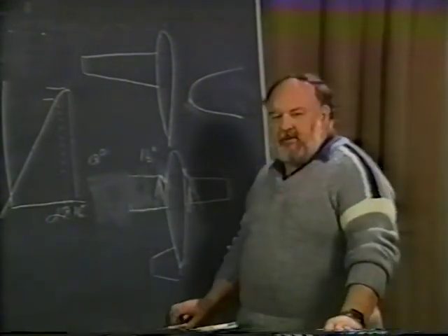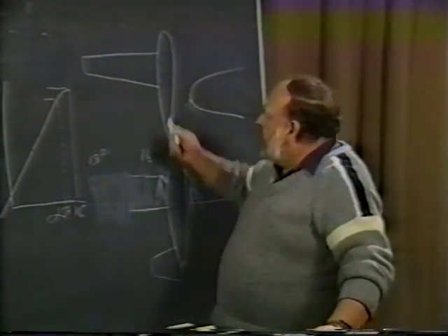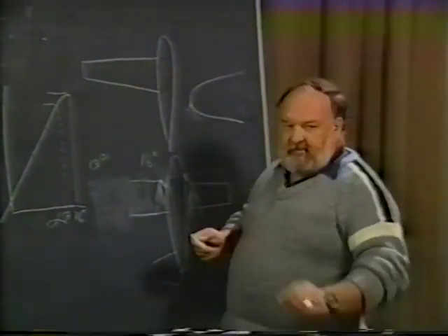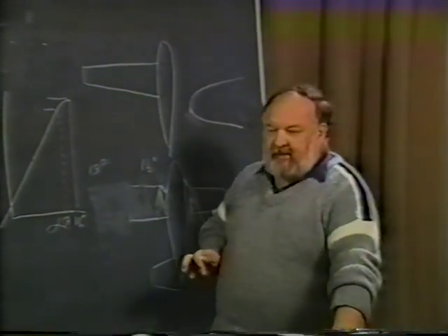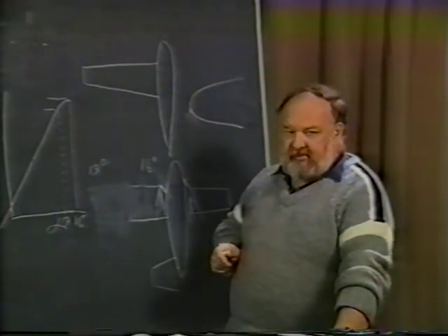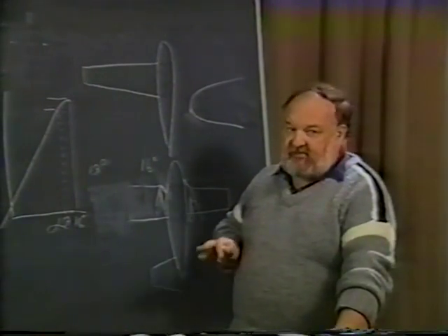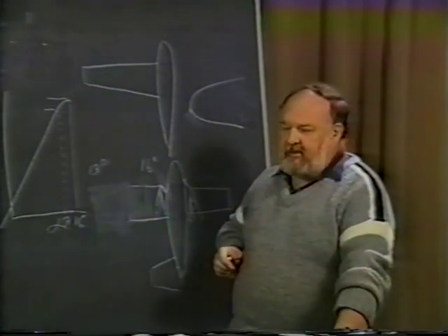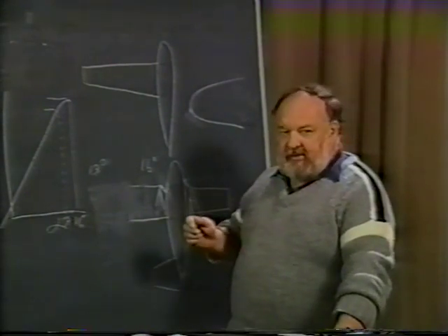Now, when we came to, say, the airplane like the Bede 5, we used a little different approach on that. We did use a tapered wing. It was a smaller chord than it was at the tip. And we're well aware of the fact that this tip now had a lower Reynolds number. And we're well aware of the fact that this airplane was going to go quite fast, so we did not want to put any twist into the wing. But we still wanted to have a good stall pattern. Well, what was the technique that we used there?